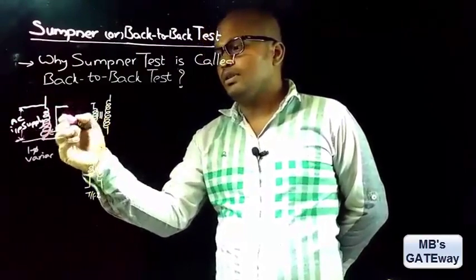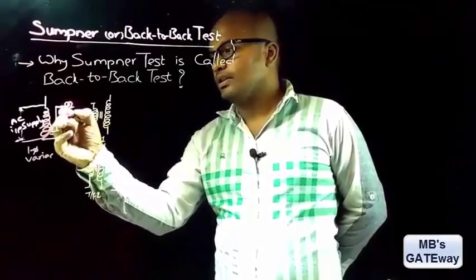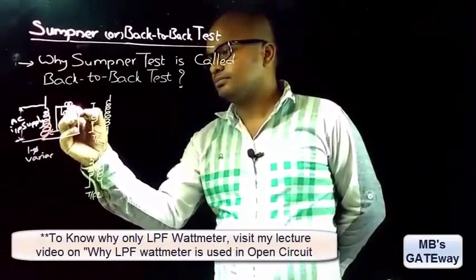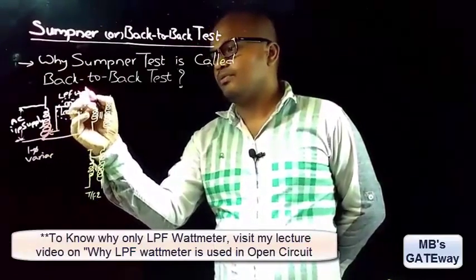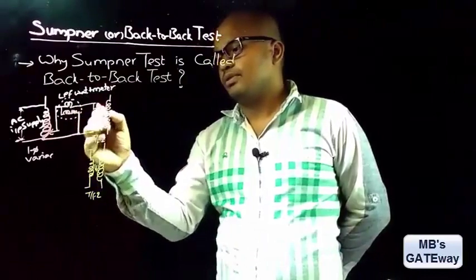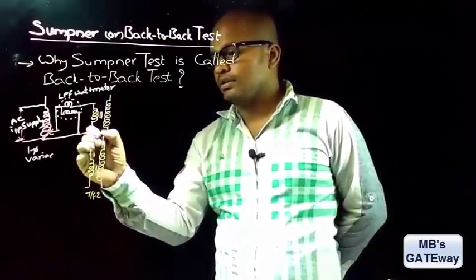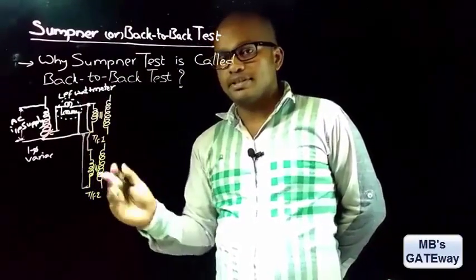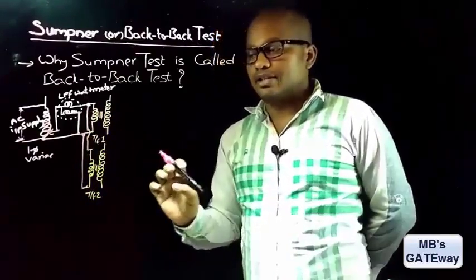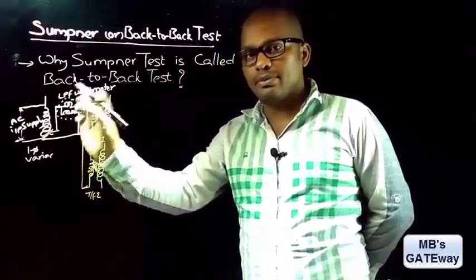And to measure the input power taken by these transformers, we are connecting an LPF wattmeter. So now the input is given to the primary of transformer 1, and the primary of transformer 2 is connected like this, which means the primaries of the transformers are connected in parallel, and the power taken by these two transformers is combinedly read by this LPF wattmeter.